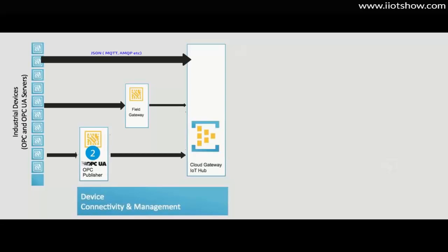Okay, now using an OPC UA client deployed on the cloud allows you to visualize and send commands to the plant directly from the cloud, right? In this case, your solution may include an OPC UA proxy module at the edge in order to handle communication and authentication between your cloud-based OPC UA client and your OPC UA devices on the plant floor.